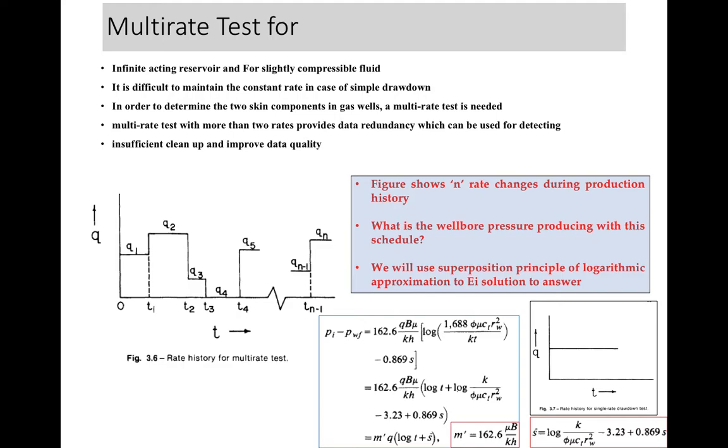Now the question arises: what is the wellbore pressure produced with this schedule? You want to estimate the wellbore pressure. With such a schedule, it is very difficult to interpret that directly. And to answer this, we have the superposition principle, and it works in the same way as we discussed in